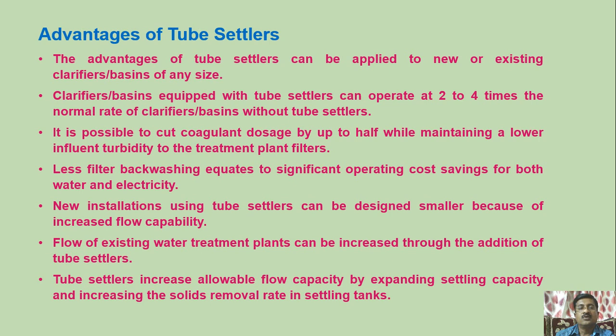Now, what are the advantages of tube settlers? The advantages of tube settlers can be applied to a new or existing clarifier basin of any size. Clarifier basins equipped with tube settlers can operate at 2 to 4 times the normal rate of clarifiers or basins without the tube settlers.